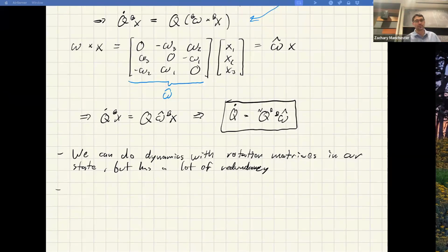So it turns out quaternions, which are also singularity free, are only 4 degrees of freedom, or 4 numbers. So they're a lot more compact and efficient. So it turns out they are preferred. That's correct. Yeah, 100%. Q dot can be 0, right? If I'm not moving, Q dot is 0. So, okay, quaternions are more compact and efficient for doing dynamics calculations with.